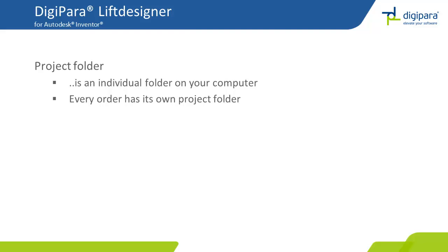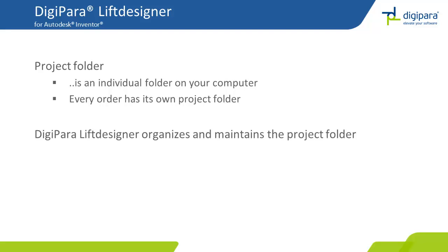And finally, we are talking about the project folder, which is an individual folder on your computer, and every order, every elevator project that you create will have its own folder. We recommend to have this folder on your computer. Do not put it on a server, because then you have strong performance limitations. It's recommended at the end, when a project is completed, that you check that into Vault, or that you copy this on a network drive for backup purposes.